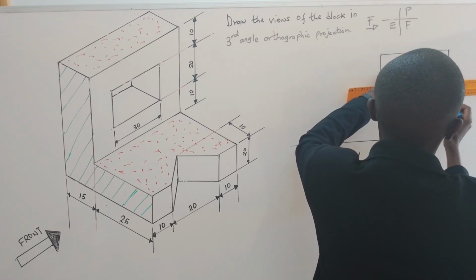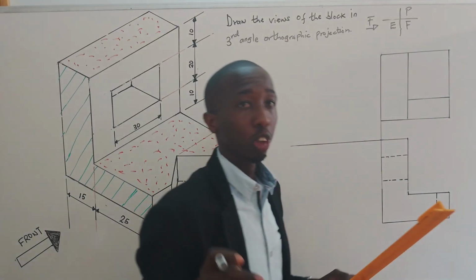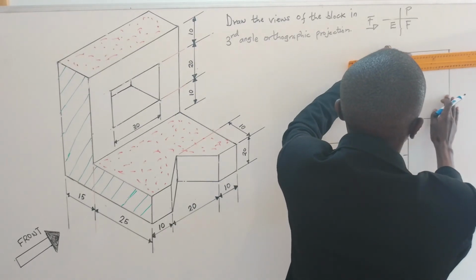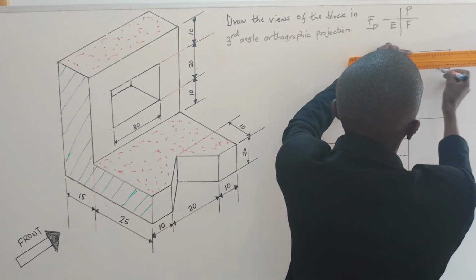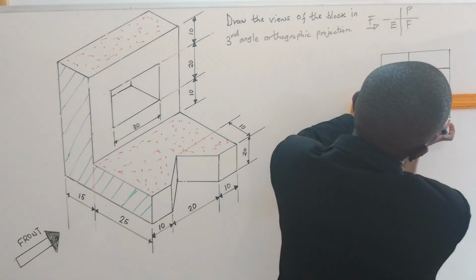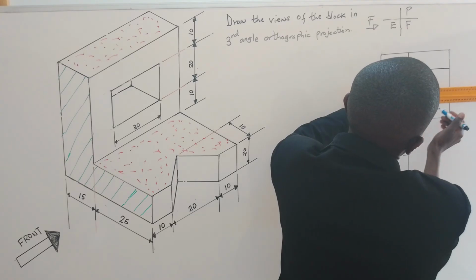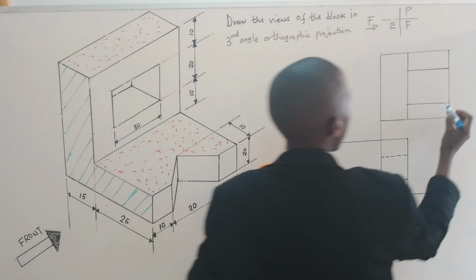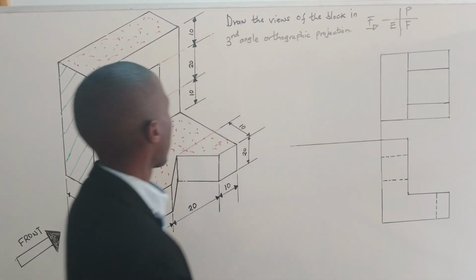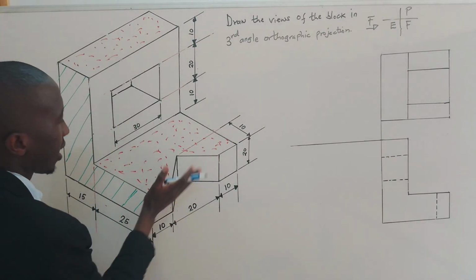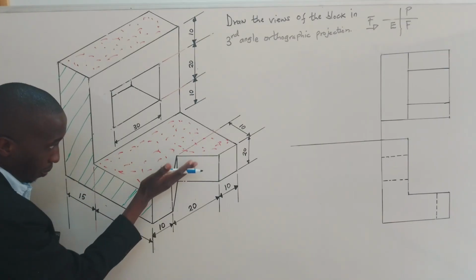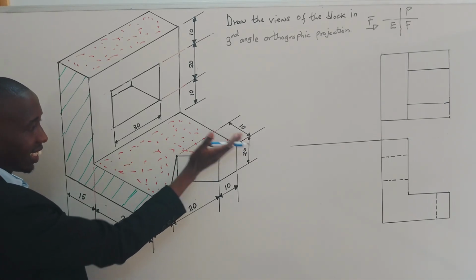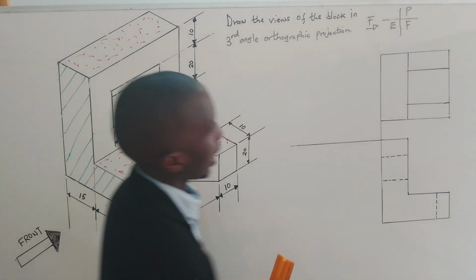And then do a horizontal line first. Maybe you can use a construction line. Let me make this small. So you measure 10 and you mark from the top, measure 10 here and then measure from down going up. So I will mark this here. Now from there we want to do an offset. We will do an offset from this face there. So we have an offset of 10. So this corner is located at 10 going inside. So I will mark 10.